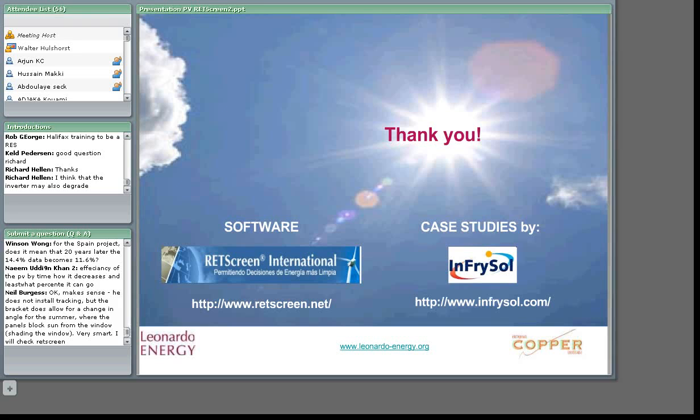Yeah, sure. But in this case, if you want to estimate generation, then you should split the estimates from RETScreen with different angles applicable for different months. So in this case, you should build by your own your generation curve along the year. But indeed, this is another possibility. Explicitly, RETScreen doesn't allow for that, but you can build your own model by taking the results from RETScreen on month per month basis for a given angle.